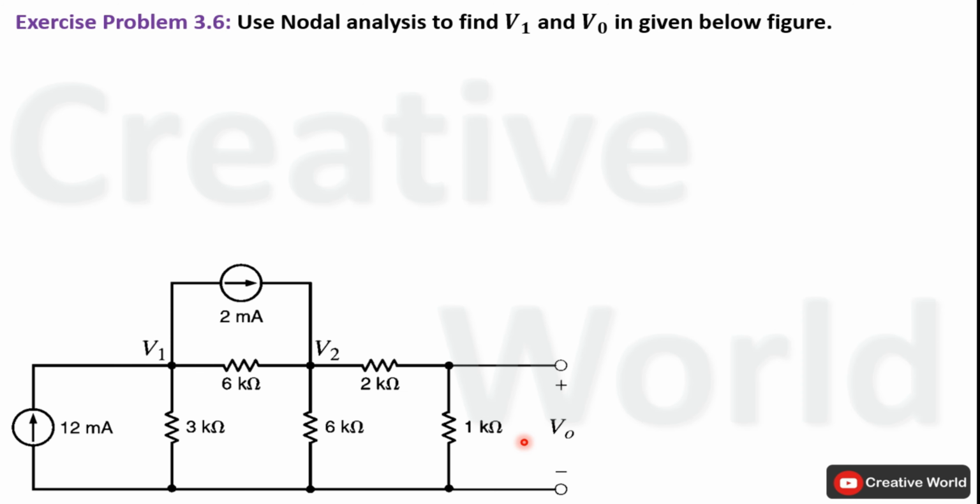We know that in order to apply nodal analysis on any network, we have to follow some steps. The first step includes finding out the maximum number of node voltage equations that can be retrieved from the network. Using this equation, we can find out this figure. In this equation, n represents the number of nodes that exist in the network. In this network, there are 4 nodes, so a maximum of 3 node voltage equations we can retrieve from this network.